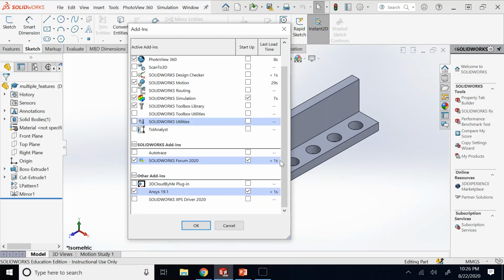So I guess I mentioned it, but if not, whatever CAD file that you make in SolidWorks, you can export to be used in MATLAB. Your SolidWorks files, there is an add-in called Simscape Multibody Link. You download it from MathWorks. When you install it, it adds here, and then it allows you an option over there to save your files in a format that MATLAB can read in Simulink under Simscape, and you can basically do advanced simulations.